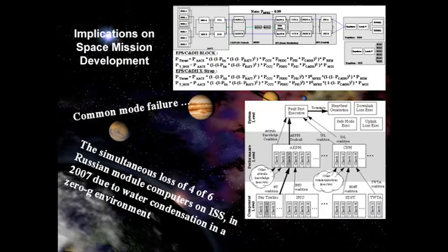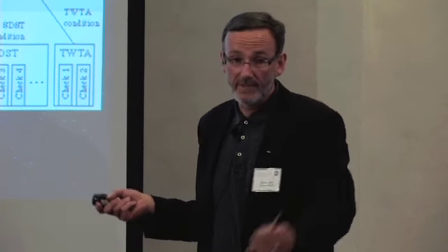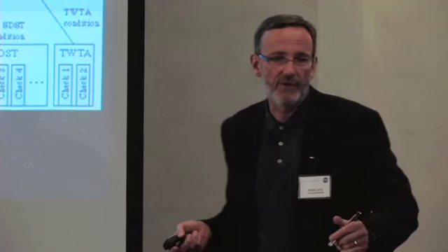The implication to space mission development is absolutely astounding right now. Common cause or common mode failure, which is something we always ignored in the past, is now upon us. Even in low-tech stuff like the 6 computers on board ISS, they had a condensation issue, if you recall, and they lost 4 of the 6 and lost control of the space station. Well, that particular failure mode wasn't on anybody's FMEA or fault tree. And yet not being on it didn't prevent it from happening, so it's a failure of imagination.